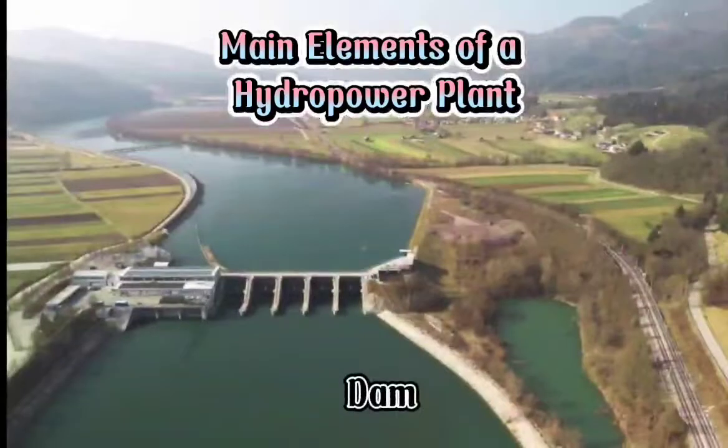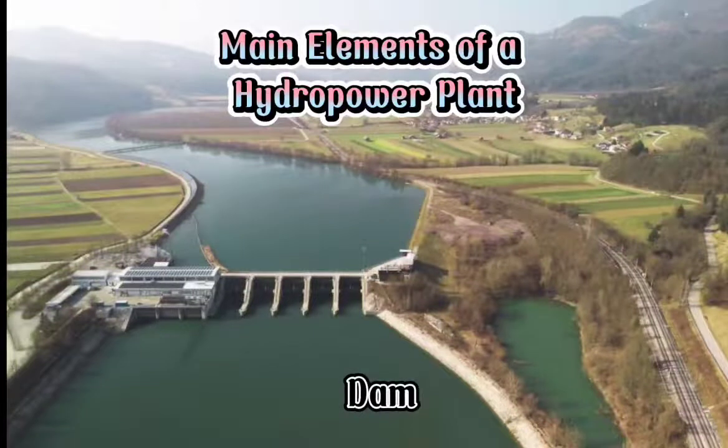Next is dam. The purpose of a dam is to offer pondage, storage, or the ability to divert water into conduits in addition to raising the stream's water surface to create an artificial head. The most costly and significant component of the hydro project is a dam. Dams are constructed using earthen or rock fill, concrete or stone masonry.